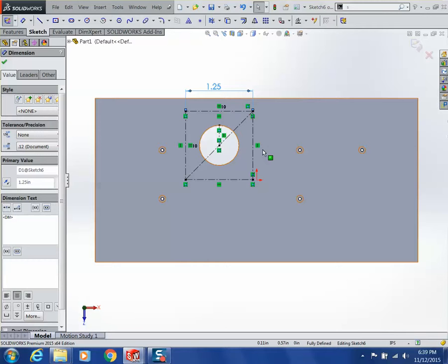If you do the center rectangle, you just hover over the edge of the circle, then go to the middle and pick the center of the circle, and then do it. You don't have to draw yours to that. Yep, exactly. You could put the box in first and then drop your sketch points back on. That actually puts a hole on center too, because it's considered a point on center. That is correct. I forgot that.